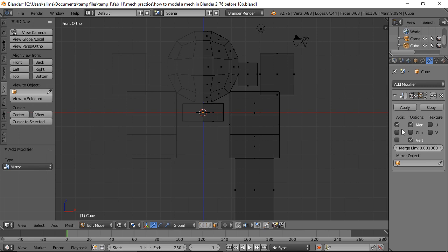These are the options for our mirror modifier here. So we're going to put a check mark here for clipping. This keeps the virtual part of our geometry from pulling apart from our actual geometry. Then I'm going to click this button right here, and that pretty much makes the virtual geometry respond extremely similarly to our actual geometry right here.